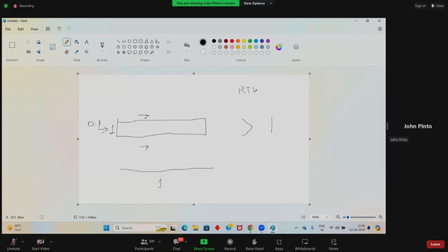So in RTD, what we are going to do is inject with some velocity, and we are going to monitor when the scalar reaches the end. Okay, that will take 10 seconds, as I explained. In the second case, with velocity, we are also going to add the source term. So my concentration will be 1 at the inlet. Along the length, this concentration will decrease.